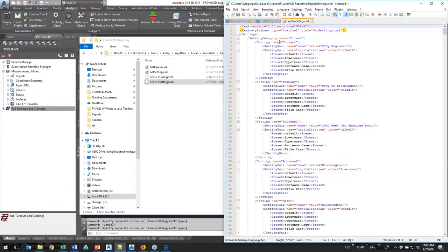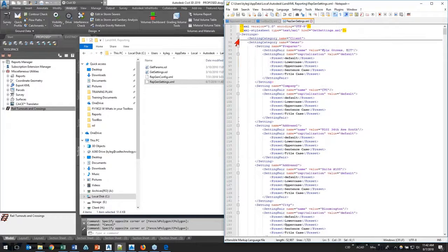But when it says, who's the client contact, well, that value's already been populated by the engineer. And if it's looking for the owner who made this, well, I did. So some of this information can be pre-populated and pre-filled out. So you might want to leave that blank for your enterprise level one, at least right away when this writes out to people. So you're going to fill in your project information and so on and so forth. But you can also modify the values for what you want these prompts to be.